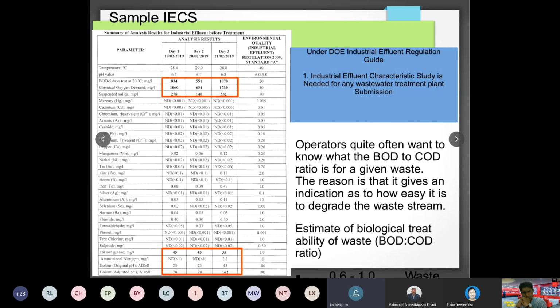And for another example, just now we mentioned you have activated sludge. Activated sludge is a living organism. It starts to consume food every day. Say you have a few days, there's no food for them to eat, and this bacteria start to have problem. That's whereby we come into the picture and advise customer to feed in some sugar as a temporary solution.